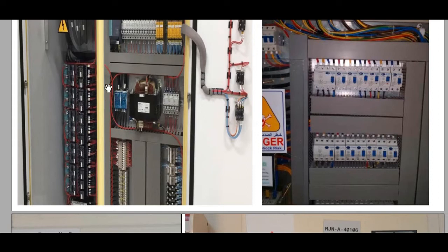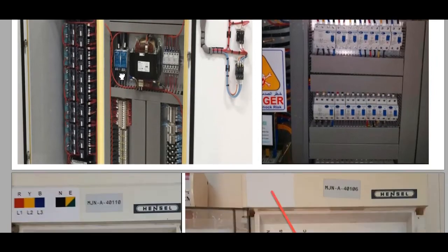It must be made into a bunch, and after that, whoever is responsible for this maintenance must also remove all the covers of the cable trays and reinstall the wires inside the cable trays, then close the covers. After that, you check again by yourself, then you can remove the punch list item that you put in the primary electrical inspection report regarding the visual inspection.